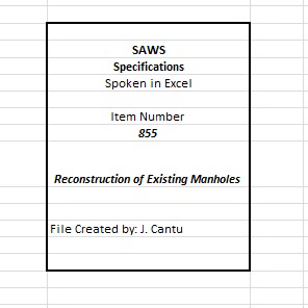A. Approved manufacturers, as listed in the SAWS APL, have previously completed required inflow leakage shop testing and have met a maximum allowable leakage rate criterion. B. Nominal cover diameter shall be 32 inches, with 30-inch clear opening, as required by TCEQ. C. Vented manhole covers will be specified by engineer.